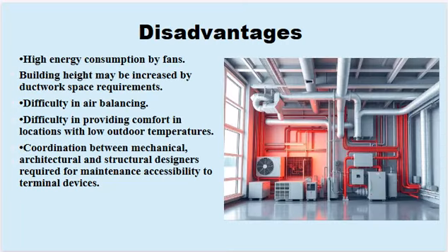Now let's examine some disadvantages of HVAC systems. First is high energy consumption. HVAC systems require large fans and motors, which can lead to significant energy use, especially in bigger buildings. Next, increased building height due to ductwork. Central systems often require extensive ductwork, and this can add to a building's height and, in turn, the construction costs.